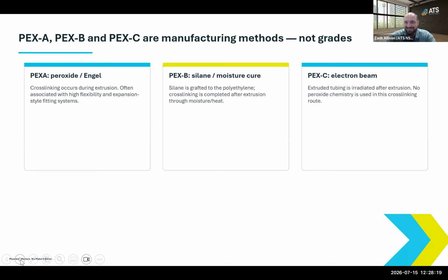That's great. But we have to really pay attention, because a lot of people have approvals, but it's only if the pipe is insulated. So the actual insulation is giving you the approval, not the pipe. It's good to be aware and just ask questions. You can get hold of the manufacturer and say, hey, send me your S101, S102 approval. You've got to pay attention. It's a minefield because some people have some approvals and not others, and some pipe has that and not others. You really have to do your due diligence and your own homework to see who's approved for what.